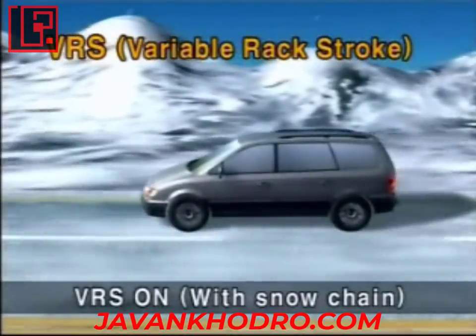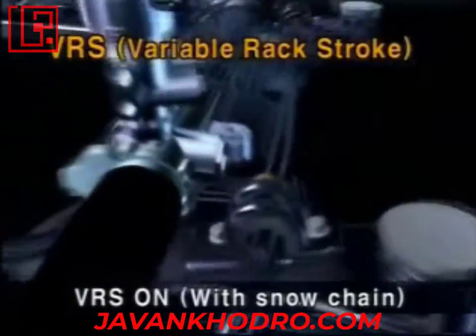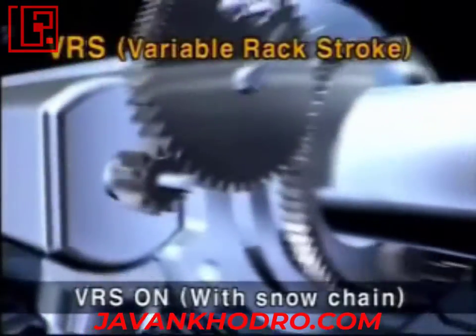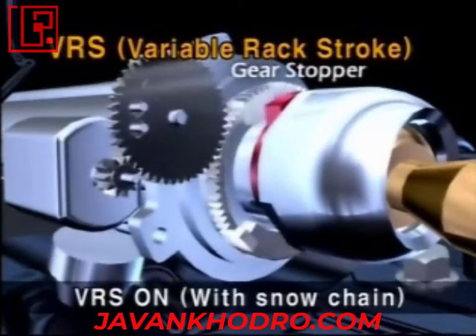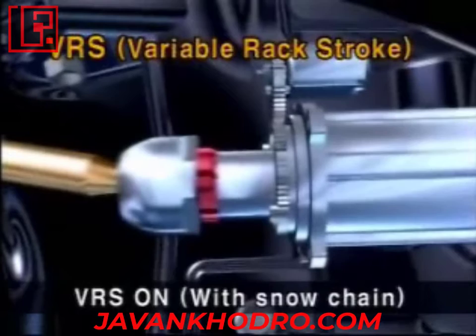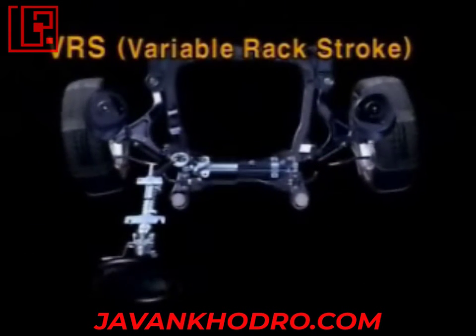When the snow chain is installed at the vehicle, the VRS operating switch is turned on to rotate the DC motor installed in the steering gearbox. The motor gear and intermediate gear are rotating. Then the intermediate gear rotates the gear stopper to change the stroke so that the steering amount is reduced while parking or U-turning.